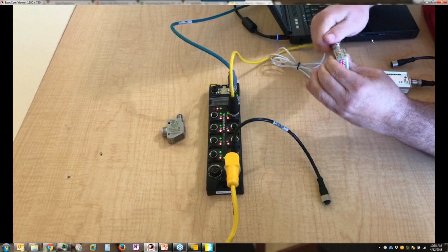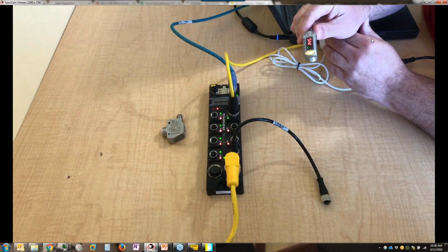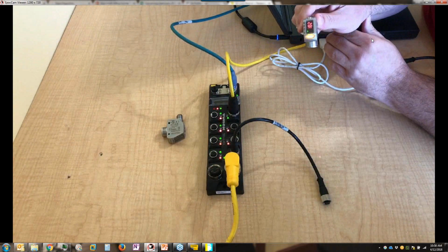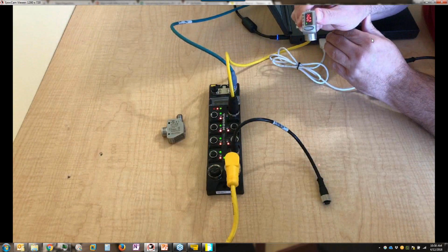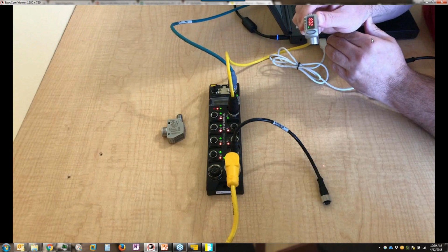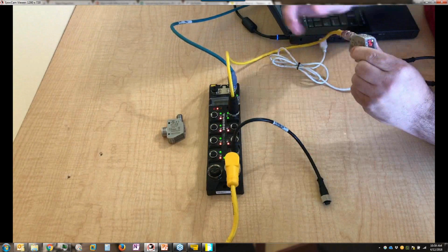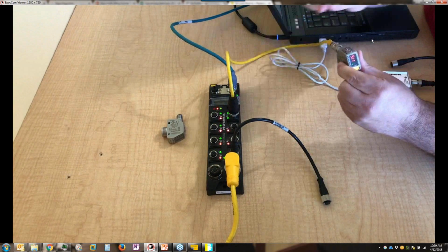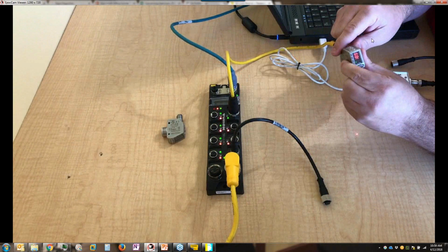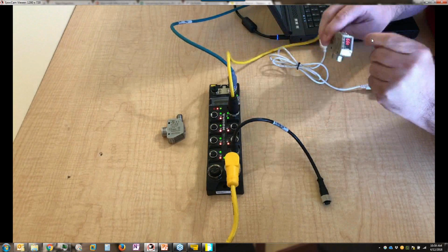We know that this one was set up for 150 millimeters, but now, look at that. It's now reading at 200 millimeters as a sensing point. What happened is, as soon as I connected the unit, the master was able to determine from the newly connected IO-Link device that, hey, it's time to restore the parameters back down to the device.